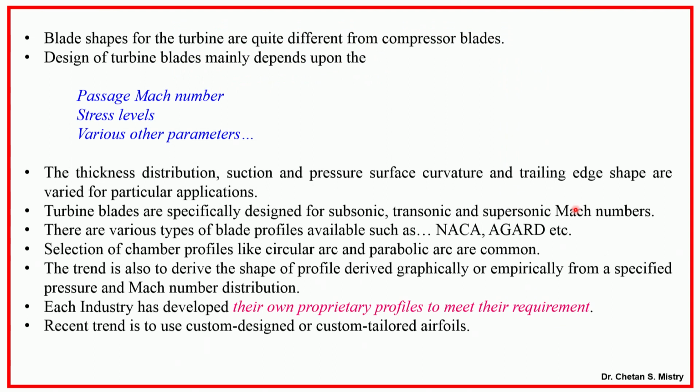So, the thing is, now when we are talking in terms of different profiles for the turbine, we need to have this turbine profile, which mainly depends on my Mach number, stress level and various other parameters. Strictly speaking, there are a few profiles available online or in open literature, in terms of the NACA profile and the AGARD profile.